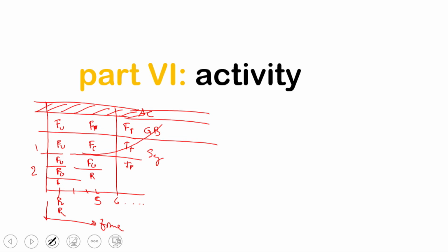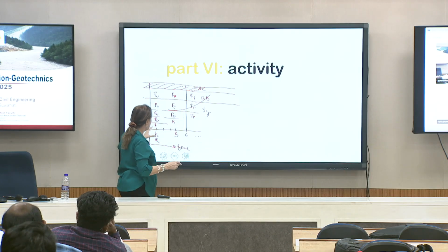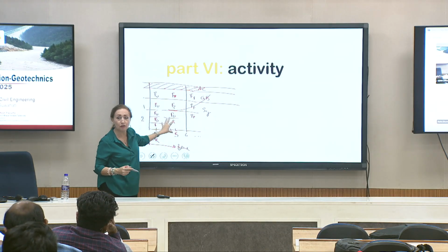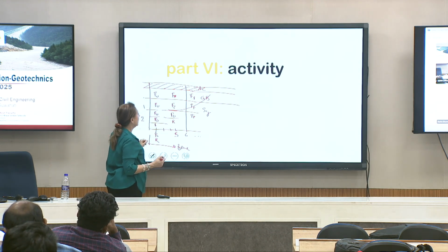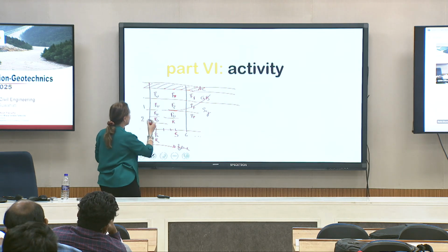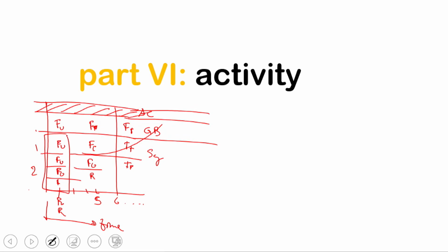So you do have that in here, and basically what you find out is for the whole layer, because you're going to need to put this one into your resilient modulus and permanent deformation models, rutting models, you're going to have a composite value of what you get in order to figure out what is the condition. Now, the composite value will be with the depth, but with the time, you can have different values, right? So you got, again, the unfrozen environmental condition, the freezing condition, the thawing condition, and the comeback.